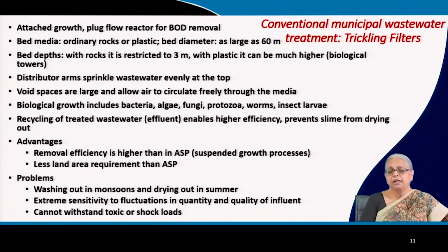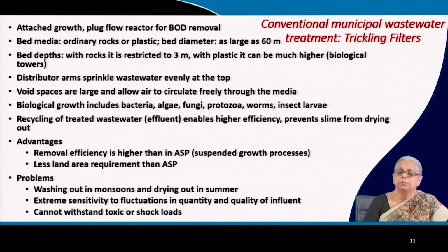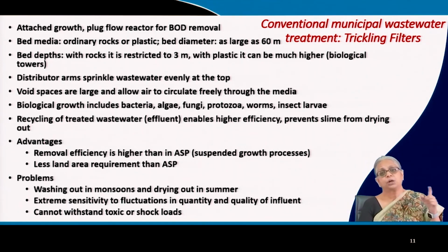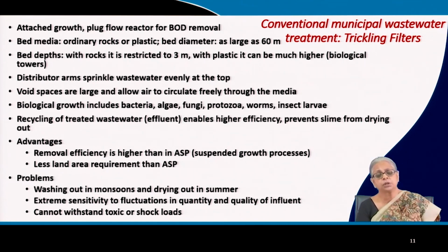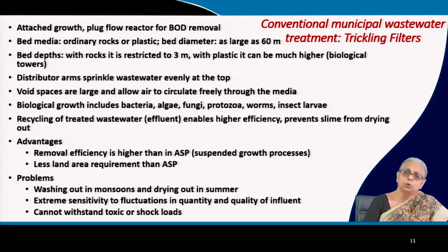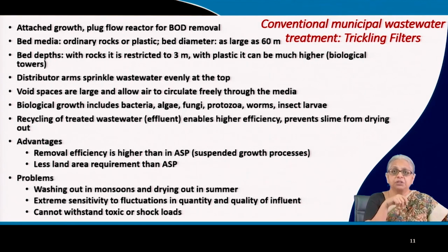Just to give you an idea, there is a little bit of information about trickling filters as well over here. So we have attached growth process. Trickling filters are an attached growth process. They generally run in plug flow mode. But if you have a significant amount of recycling of the biomass, then the greater the amount of recycling, the closer it begins to resemble a CSTR. Now, the same objective applies here as well. It's mainly designed for BOD removal.